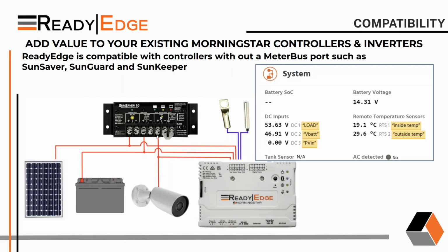If the load is low and the battery is low, you'll see that in the data, and you'll also see the load shut off with this voltage input. You also get the battery voltage from the power in. That's also a monitored value. So maybe you don't monitor your battery through this specific voltage sense. Maybe you want to use that for something else. And in this simple example, we also are going to use a few temperature sensors, one to monitor maybe the battery or inside the box, and one to monitor outside or something else.